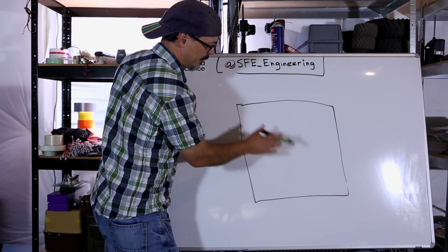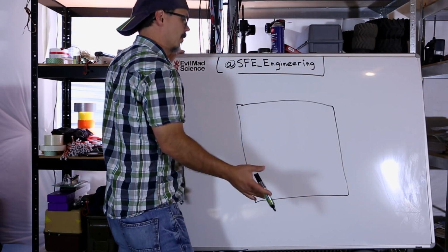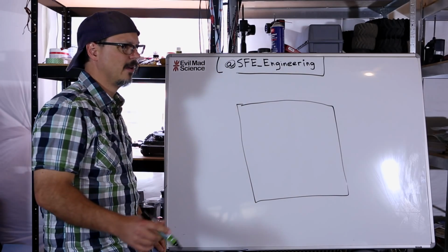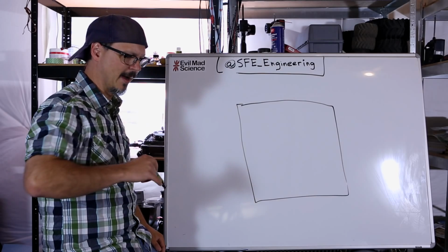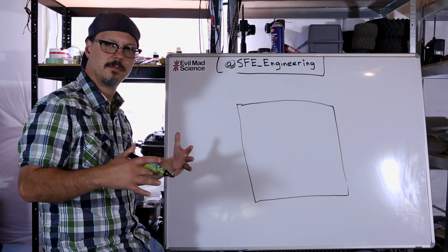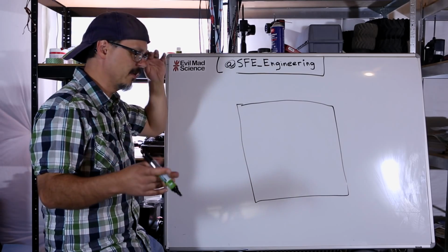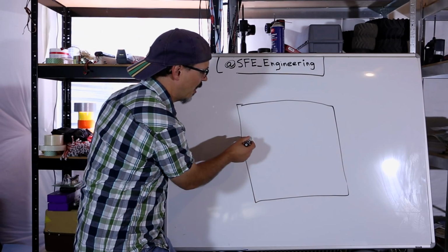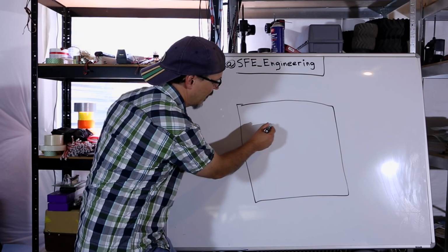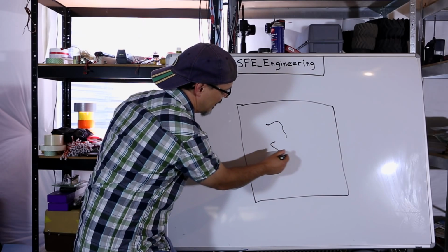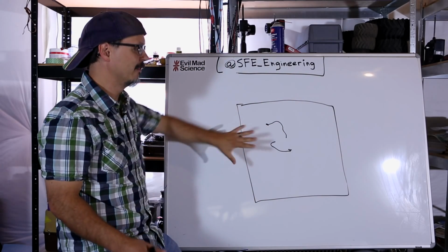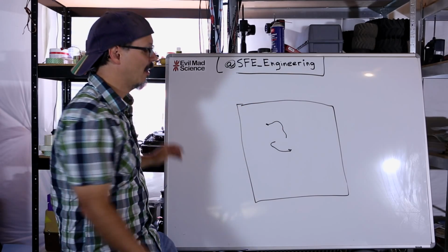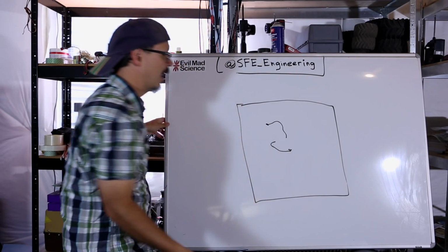So the whole bottom of the board will be copper or thereabouts. Typically what I would do is I would lay down all of my signal traces first. And some of them inevitably will go on the bottom from component to component. That's just the way it happens. You try to keep it all on top so you can keep the bottom all copper. It's never going to go that way. You're always going to have a few traces on the bottom.